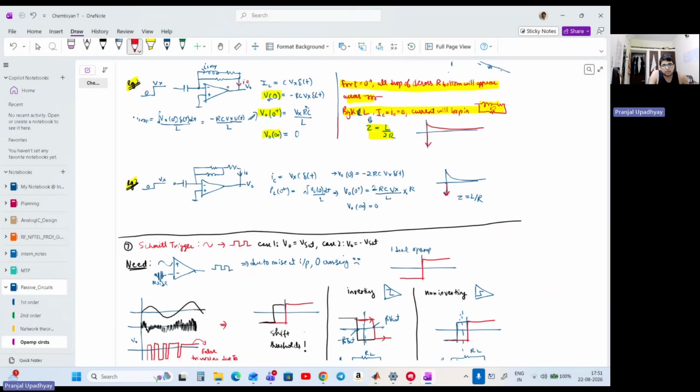And similar to this scenario, since the impulse current will cease for positive time, here also there will be no current later. So that means that the current developed across the inductor will just loop in this guy, and thus eventually, just like the previous example, this voltage also because of this loop current will decay out, right? And it will decay out with tau equals to L by R. So these are some examples I thought that we can discuss.